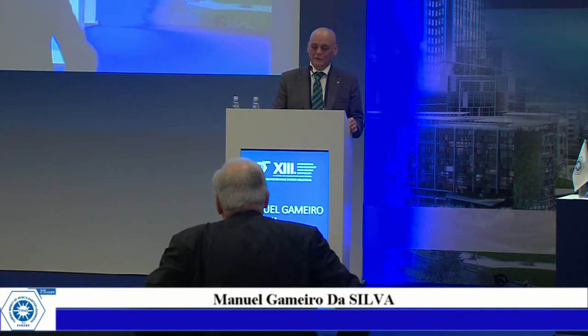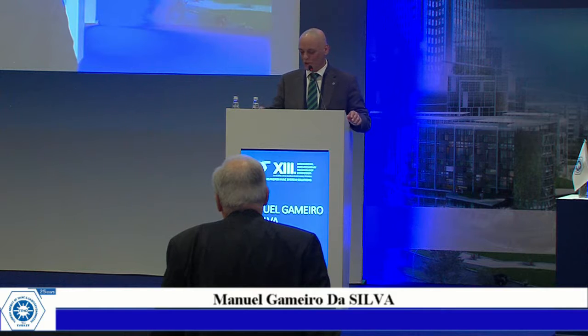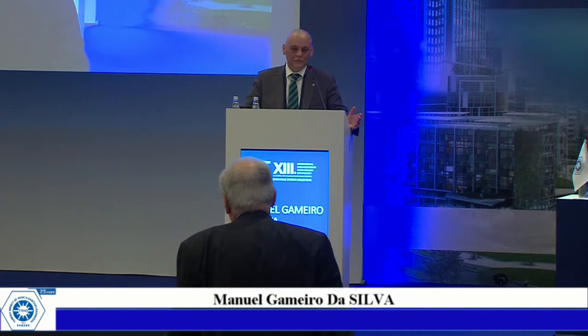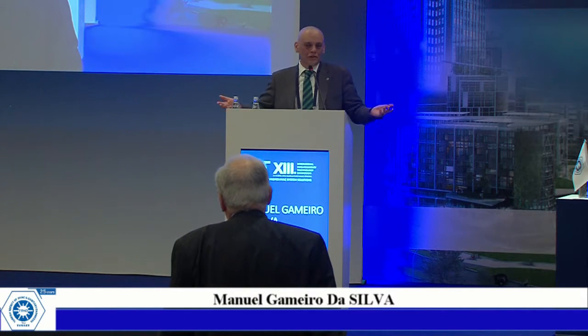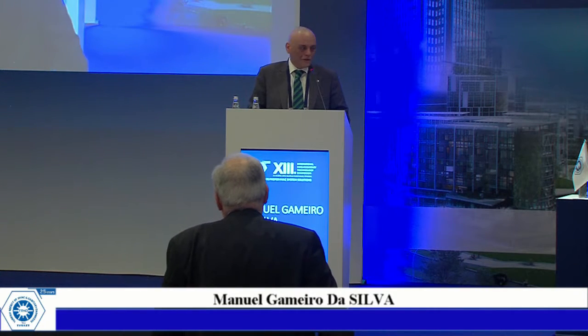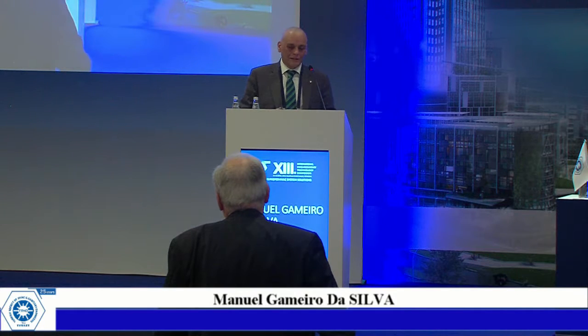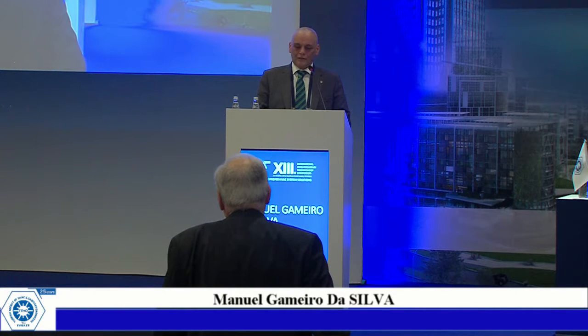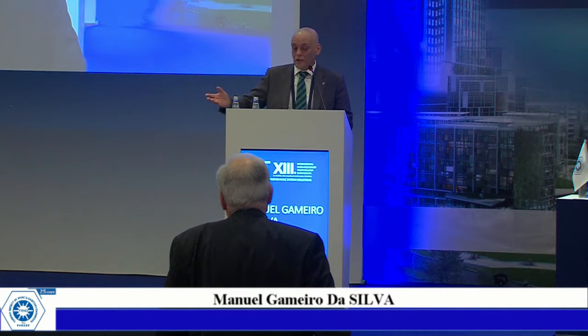Let me just give you my opinion about the adaptive model. The adaptive model is not different, for instance, from PMV. When you are using the adaptive model, it's like using PMV in a situation where you don't take into account humidity, because you consider that humidity is not so important if you are in the comfort zone and for a person with a sedentary activity.